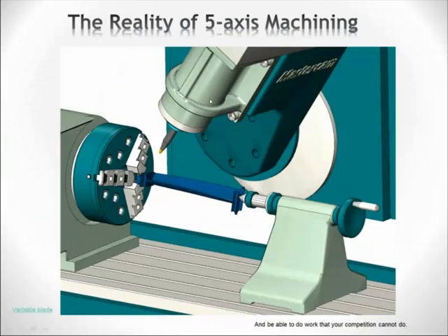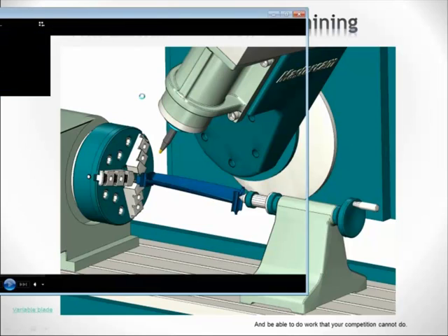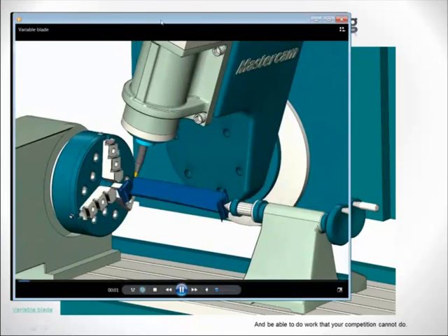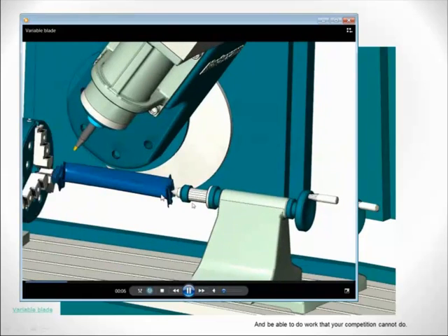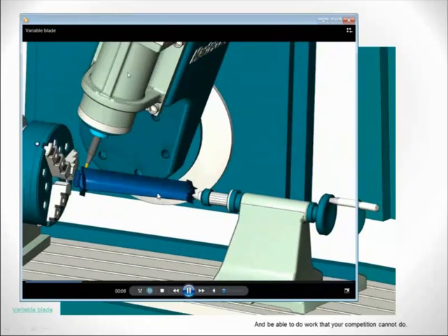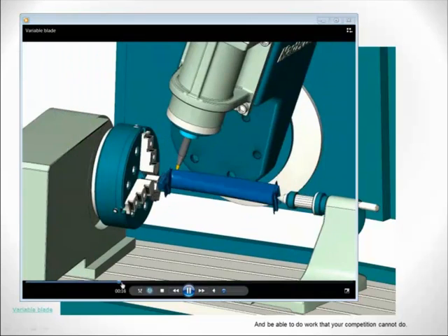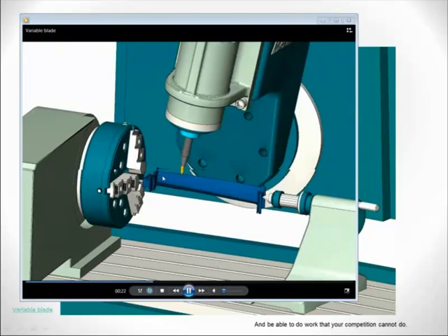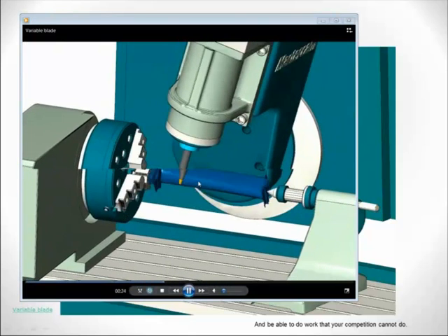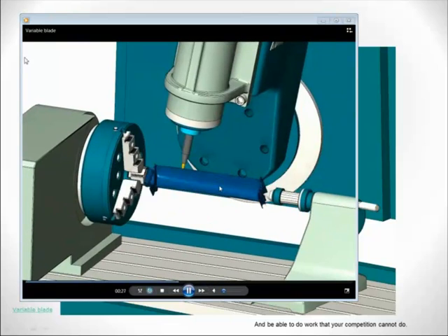And the next step would be a dedicated 5-axis machine like this. This is a Matsuura. This one has a tilting head and a rotary table. In this example, we are cutting a single turbine blade. And we're using one of the features that lets us change the angle of this head. Let me move it up here. When we're cutting on this side, we want to be able to reach this root. And as we're going down this turbine blade, we are really just doing a spiral cut on this.